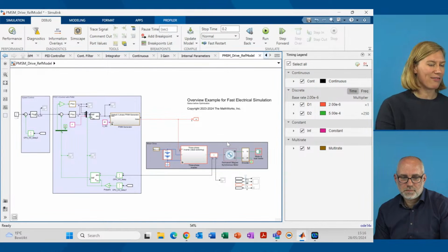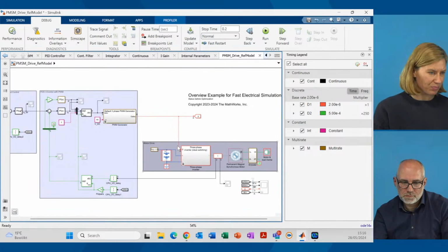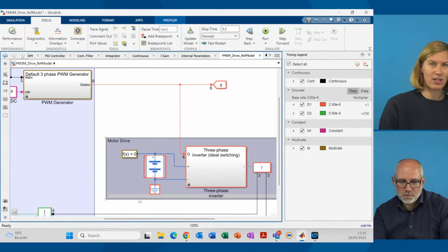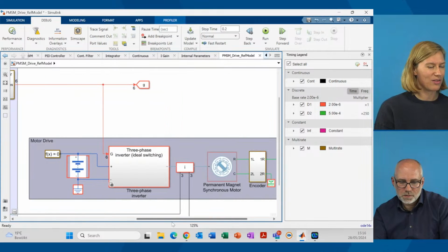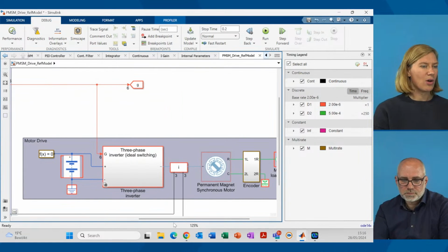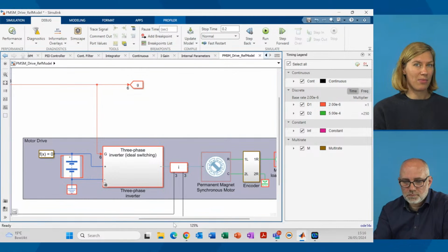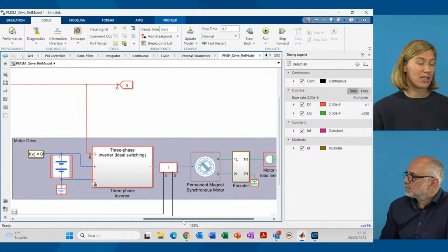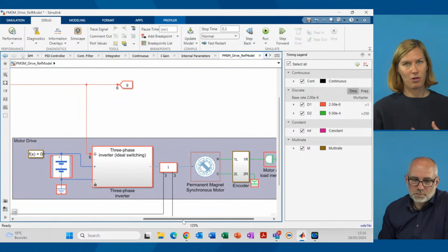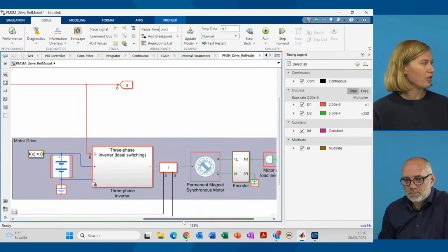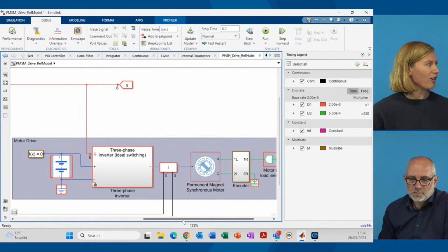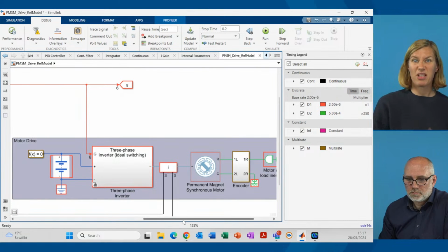So it's intended to run fixed step. And what we can also see is that the blocks are somewhat highlighted in red, pointing to the update rate. For Simscape, there are a few cases where you would run the Simscape model at a fixed step rate. For example, if your plant intends to do a HIL simulation and you need to generate code for that, or for some models where you have a lot of switching going on, it might make more sense to run in fixed rate. But oftentimes, when we're doing more desktop simulation, as we're doing today, you would